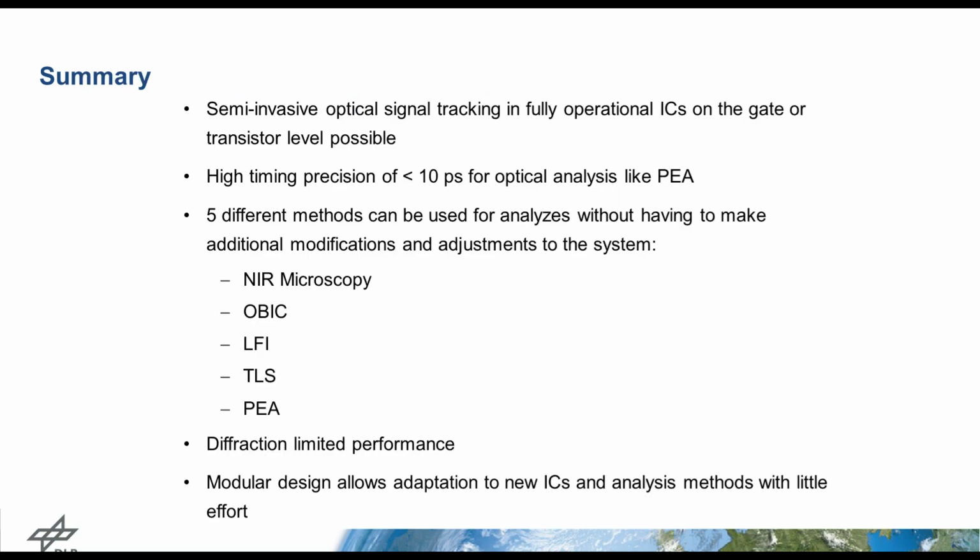So with this, I come to the end of my talk. I showed you our setup, and with the last slide, I showed you that we are able to track the signal in an IC by an optical measurement in a fully operating IC on a gate and transistor level. By using this kind of temporal super resolution, we achieved a timing precision for these optical measurements of less than 10 picosecond. And yeah, this is quite nice.